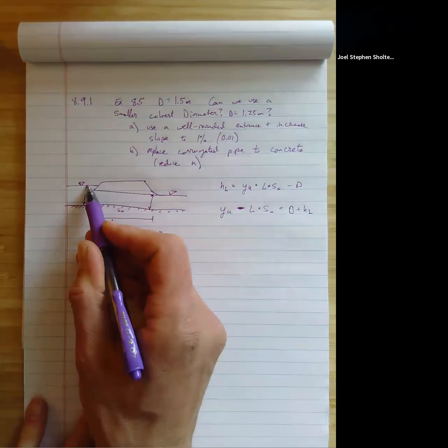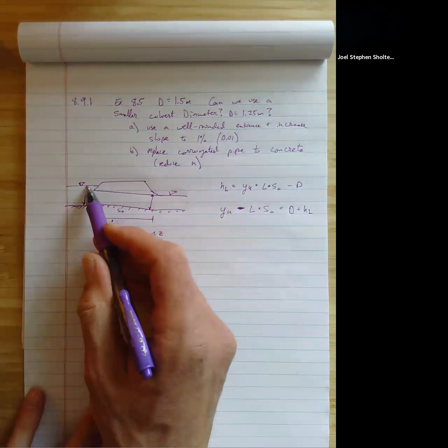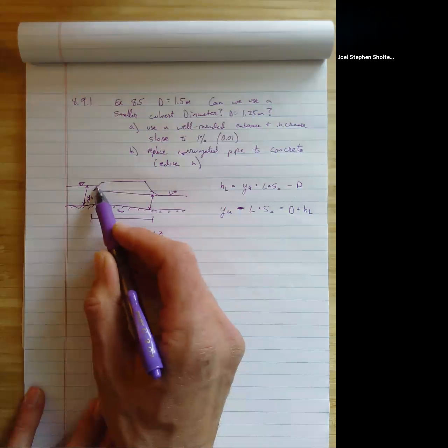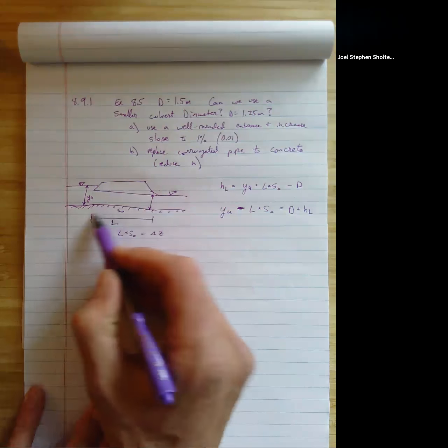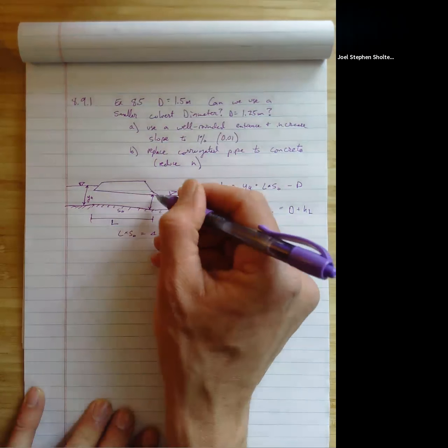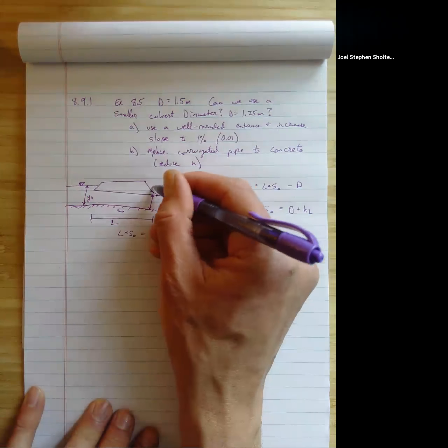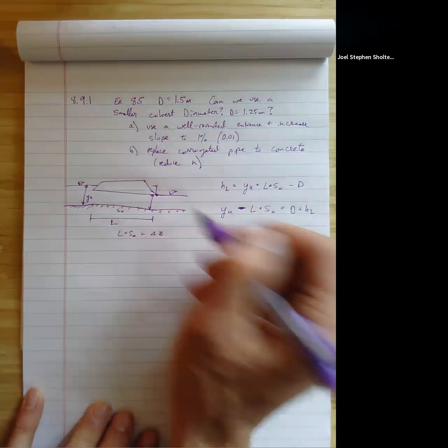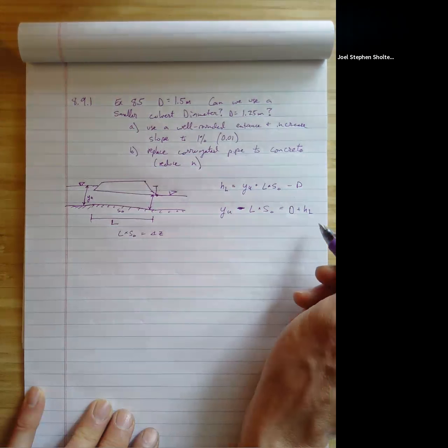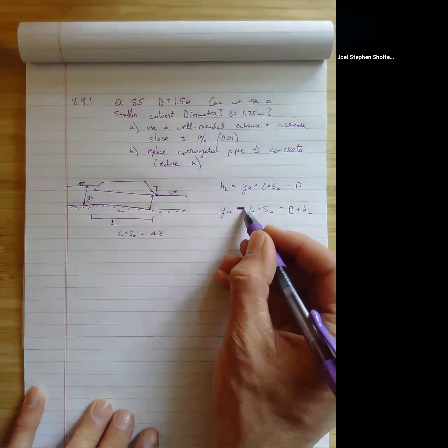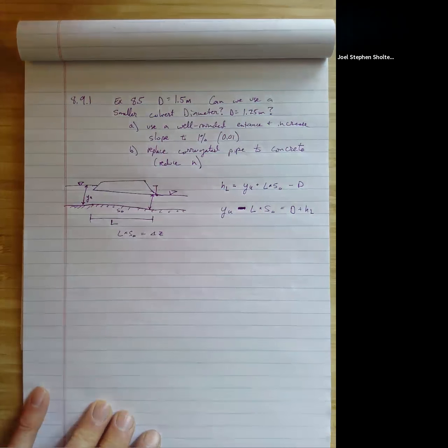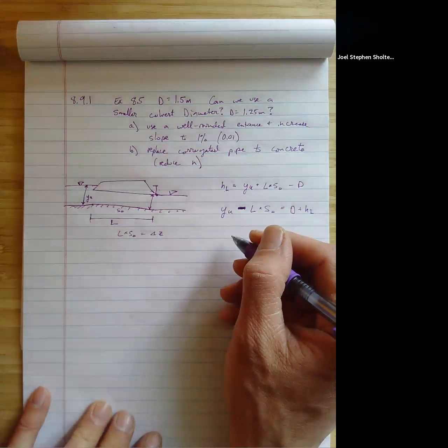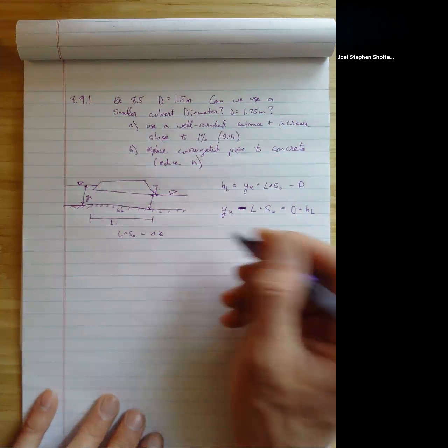We have our energy up here. We're assuming there's no velocity head. So we have our energy up here, and then we drop from here to here. We're dropping just that delta Z from the bed slope, right? We've got the diameter, so that's going to be the delta between these two, the top of the water surface. And then we have some head loss. So this is basically just an energy balance equation between the two. So we're just rearranging and solving for head loss up here, okay? So we actually directly solve the head loss using this equation.